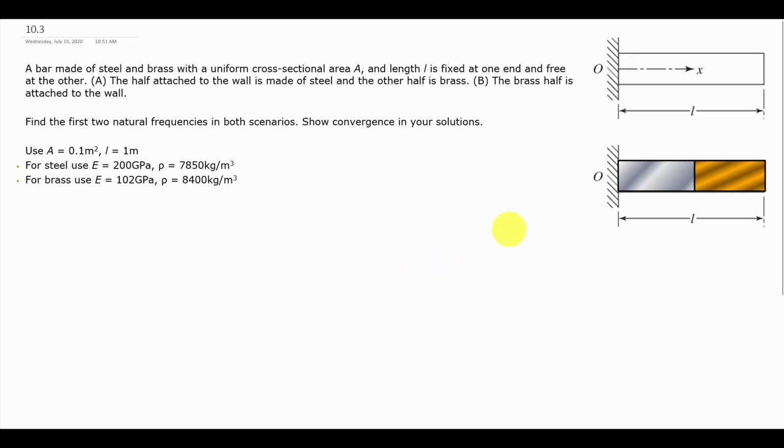Now we're going to look at an axial bar where the material is going to change partway through. So this is going to fall outside of what we can solve analytically from the previous section, where we needed constant material, which is to say we needed a constant Young's modulus and density in order to use the PDE and the solution that comes from it. And in this one we have a constant cross-section though, so at least the A is going to be constant all the way through.